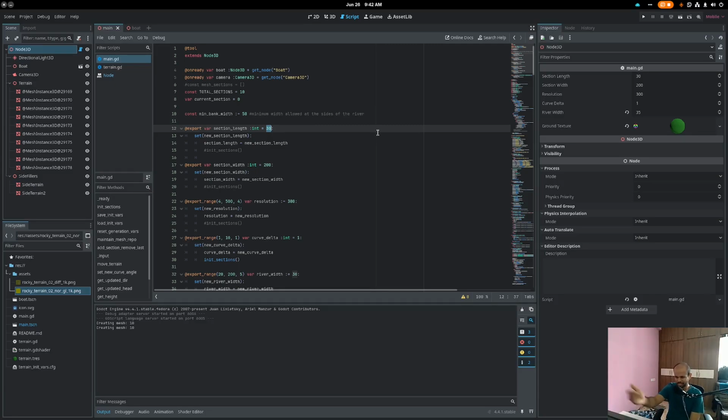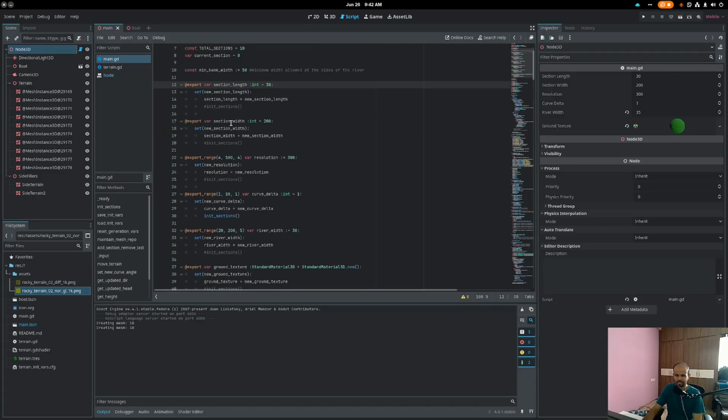It shouldn't go past the last section. That's how I set this. And you want the lengths to be short so that it takes less time to calculate each section. But not very short, of course, because then it will take a lot of sections to build up your whole mesh. So you need to just play around with that a little bit.